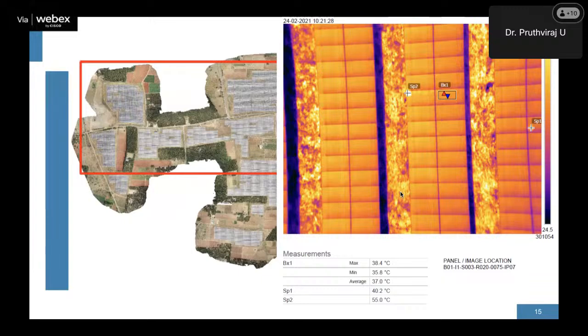Nowadays it is very popular to have solar farms. If you see the solar farm here, there are a lot of panels on 8 acres of land, and it needs to be surveyed. There are basically two types: one is to regularly do an RGB survey, and another is to try it with a thermal camera, or now integrate RGB along with the thermal camera and then do the survey. What will happen is that hotspots on the solar panels will be visible.